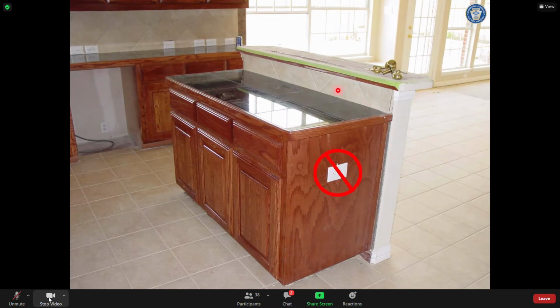And to make this code compliant, again, I took this photograph and also measured that right there. And from right there to right there, that measured 54.5 inches. So what does that mean? To make this code compliant, you'd need at least 2 receptacle outlets up here, wouldn't you? Because if you tried to put one right in the middle, you're greater than 24 inches to this point and that point.